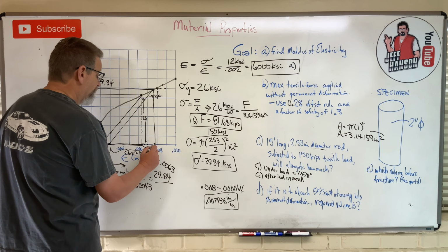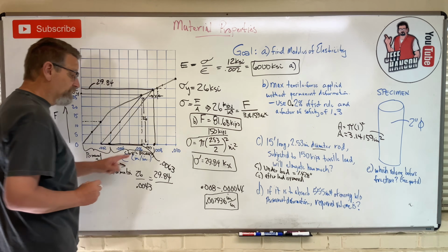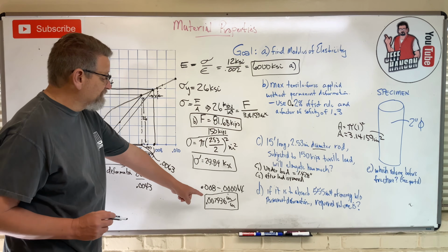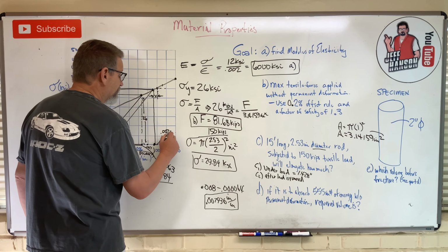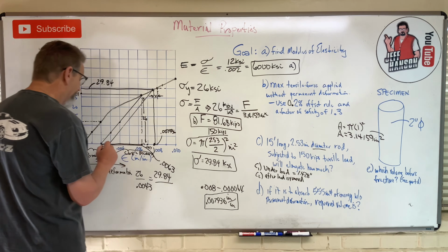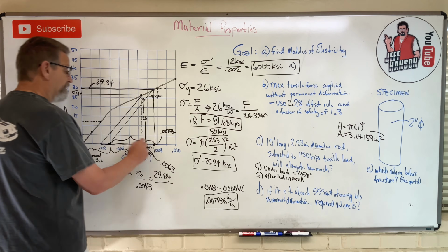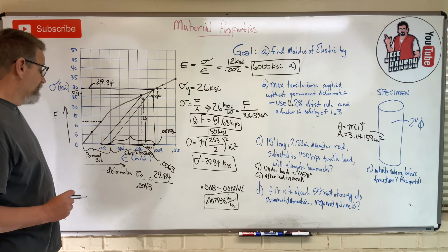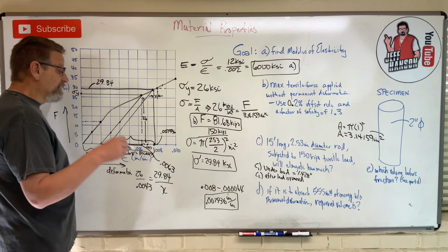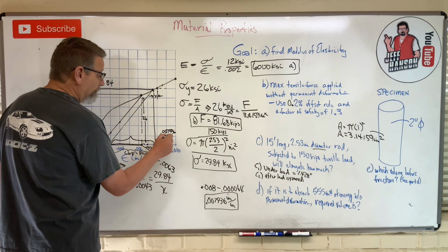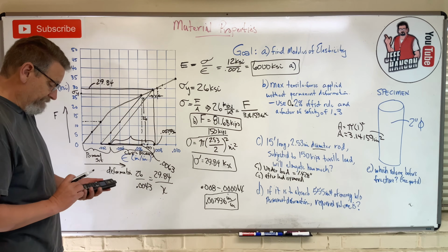I don't know. Now when I get this, it's not going to be that value, right? Because I do know what that value is. We just calculated it. That value is 0.007936. But what we're going to find is the length of that side of the triangle, okay? So we'll just call that x. Whatever we find for x, we need to subtract that off of this number, and that will give us our permanent set number, okay?